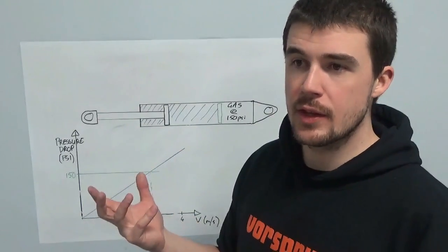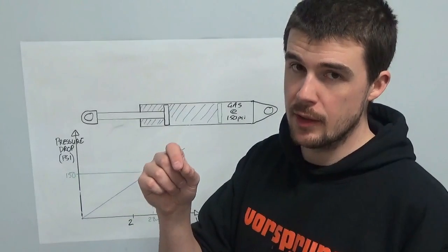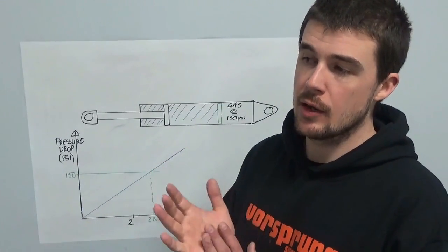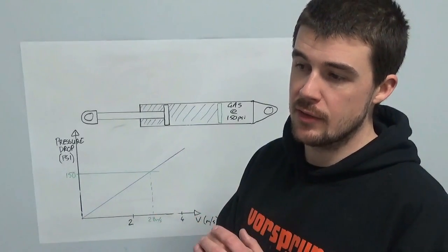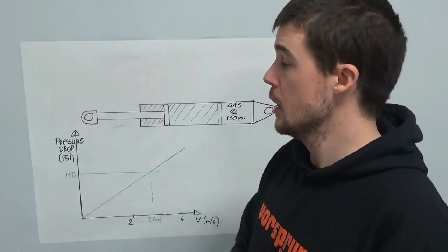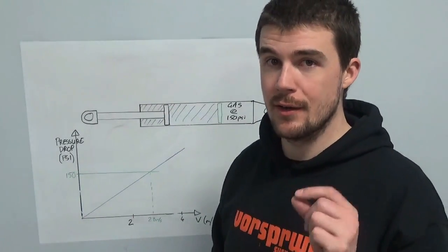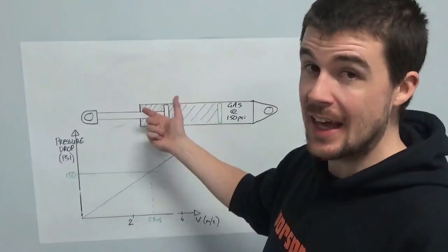It is the same sort of thing that happens with boat propellers, actually in a very localized position right behind the tip of the propeller, where the vortex shedding can create a locally very low pressure that actually means that you are essentially evaporating water. But in this case, what's happening is you are effectively boiling, very temporarily, the oil behind here. You're drawing a gap, basically a cavity.